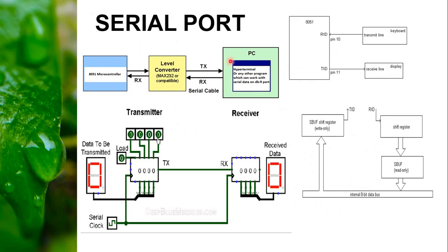Next one is the serial port. In the 8051 we have serial data, where we need to send the data bit by bit from the microcontroller using RS-232. That is one of the interfaces. Using RS-232, we transmit or receive data to the controller or a personal computer.